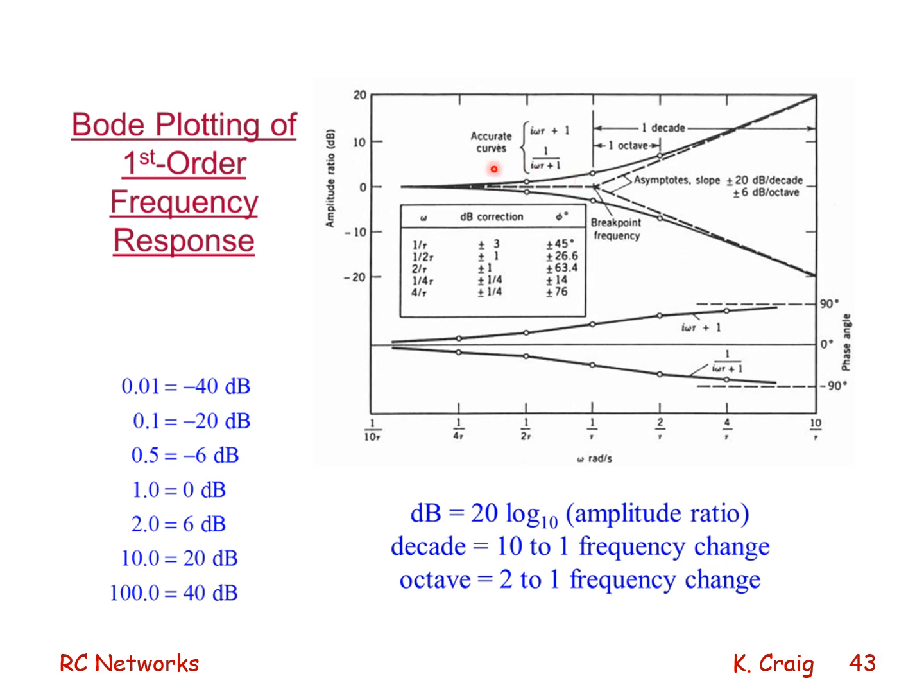If we're looking at the Bode plot for simply tau s plus 1, then it starts out flat, goes to plus 3 dB at the bandwidth, and then approaches at high frequency the slope of plus 20 dB per decade. And the phase angle starts at 0, goes to plus 45 degrees at the bandwidth, and plus 90 degrees at large frequency.